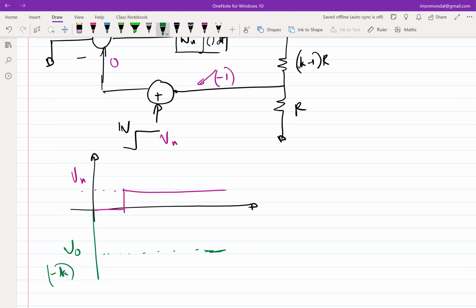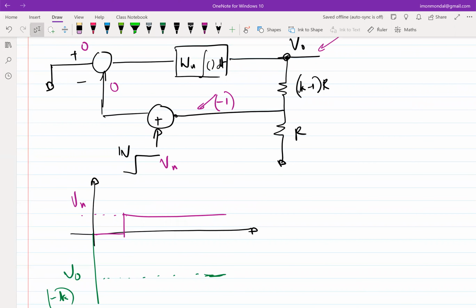So this error voltage is zero. This is only applicable under infinite gain and negative feedback. And sir, in that case, we also have to look at the output and input while identifying negative or positive feedback, right? You don't have to look at the output or input. How do you identify whether it is negative feedback or not? You break the loop hypothetically, apply some test voltage or current, and see whatever comes back, the return one, whether it is in the opposite direction to the excursion or the same direction. If it reinforces, it's positive feedback. If it goes the other way around, it's negative feedback.